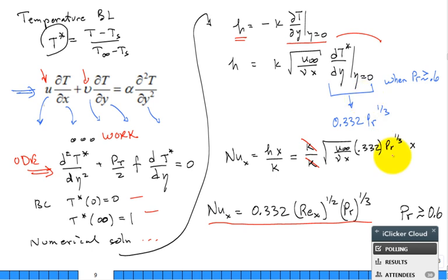You do the substitution, you get the same result, although in the analytic derivation there's a restriction on the Prandtl number that's more clear. So, you could have not even transformed to get a new ODE and then solved it numerically. You could have just stayed with the modified Reynolds analogy, same result, but there you go.